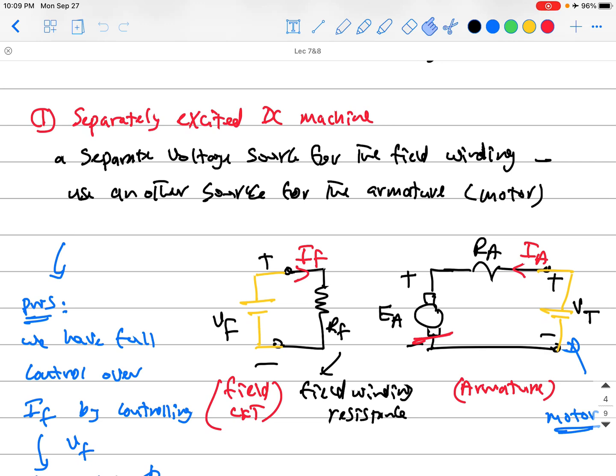The electric current moving inside the coil is the electric energy you are pushing to be converted, but it will not be converted unless you have a magnetic field, which is your medium of conversion. The same idea applies to the generator. To get generation of electric voltage, you need to push mechanical energy to rotate a coil cutting a magnetic field. The mechanical energy, the torque you're pushing from an external means, is your input energy that will be converted into electric energy, but it will not happen unless you have a magnetic field present here. Again, because the magnetic field is your medium of conversion.